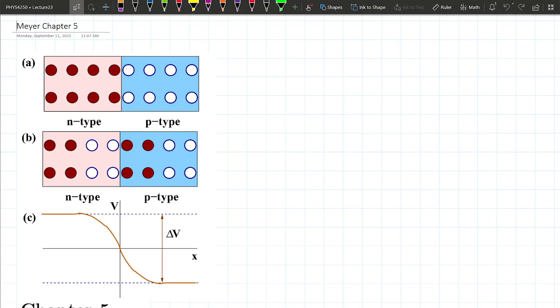Okay? So when you sandwich them together between n-type and p-type, that's when you get them to be slightly charged in this region called the depletion region, right? And therefore you have this potential across it because this is slightly positive, slightly negative. When you have positive charge here and negative charge here, it basically creates a potential between them, just like on a capacitor, right?